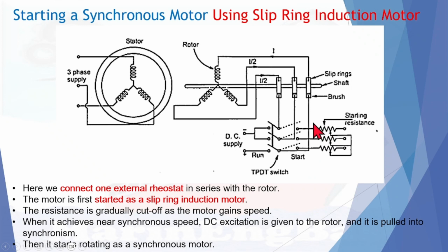Once the rotor picks up its speed and overcomes the starting inertia, you gradually reduce the starting resistance. So the running performance of the induction motor comes to an acceptable range. This is the normal wound rotor starting method. The wound rotor motors are self-starting because they have a closed path for the circulating current in the rotor.